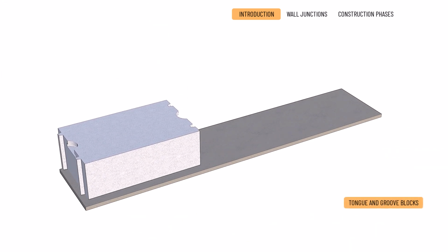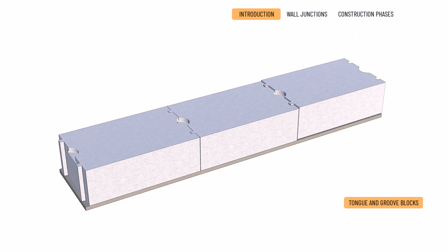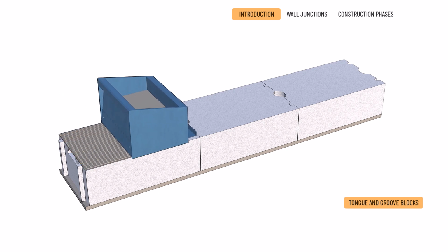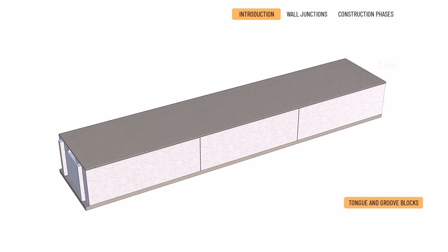However, the vertical joints of the tongue and groove blocks are already dry built. Furthermore, in this case, only thin bed masonry mortar can be used. This results in joints only 2 mm thick, which is both material saving and significantly reduces the amount of thermal bridging. Particular attention must be paid to precisely adjusting the level of the first course, similar to thin mortar solutions for clay blocks.